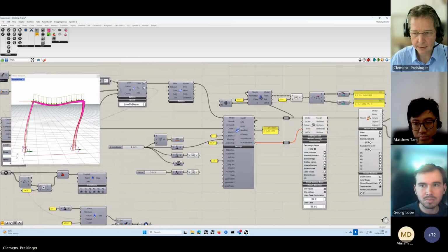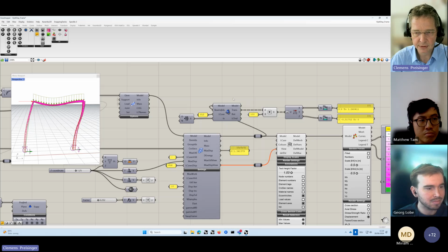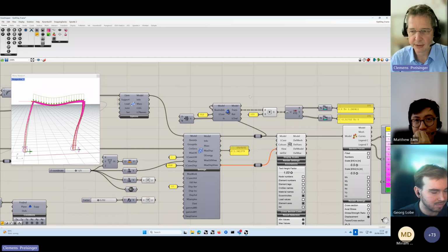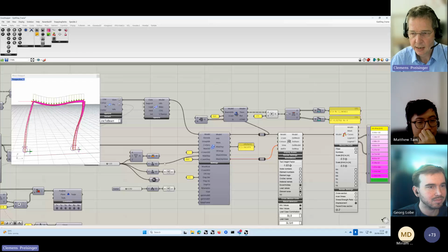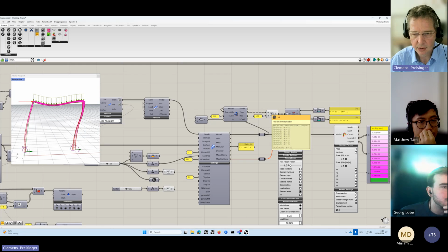I took the model and retrieved the nodal displacements from it. The frame is actually subdivided into multiple segments. So by taking those translational displacements, I get a good overall insight of the displacements. And here you can see now, first of all, I multiplied the displacements by a factor of 100. That's to go from meter to centimeter.